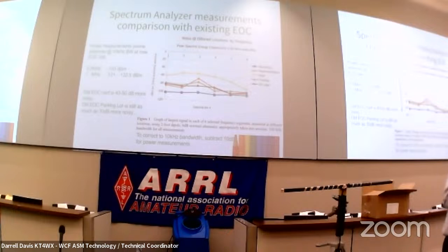That is 60 more dB of noise where our antenna was on top of the roof. 60 dB is 1 million times more noise, which means if you could receive a 1 watt signal at our quiet location, you would need a 1 million watt signal to hear it at this location. So no wonder we were deaf.